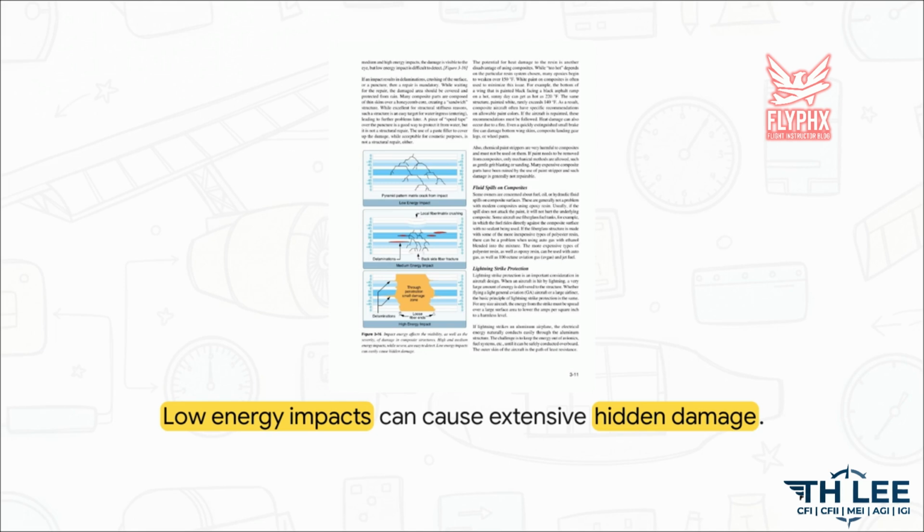Composites respond completely differently. With a low-energy impact, you get a pyramid pattern matrix crack. The surface might look completely fine to you, but underneath, extensive cone-shaped delaminations are silently spreading on the backside of the structure. The damage can be massive and structural, yet entirely hidden from your naked eye on a standard walk-around.